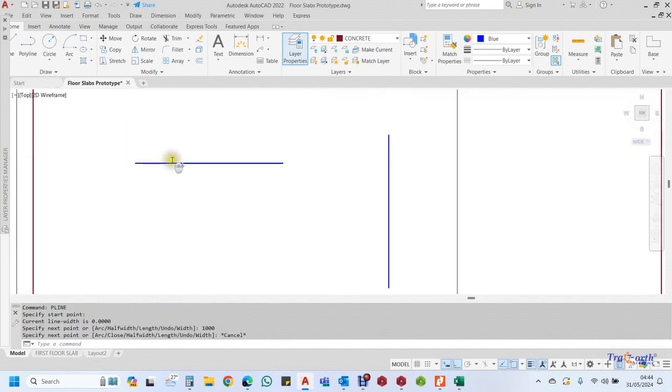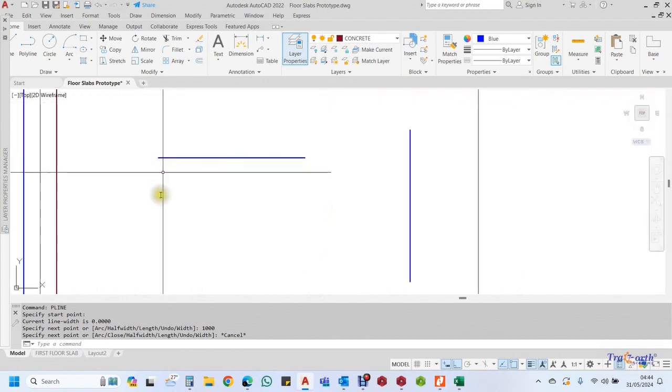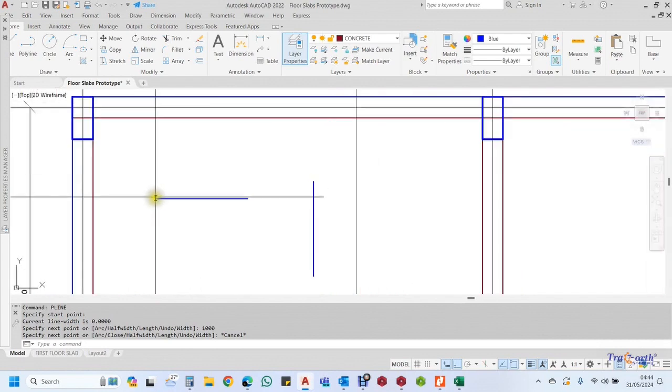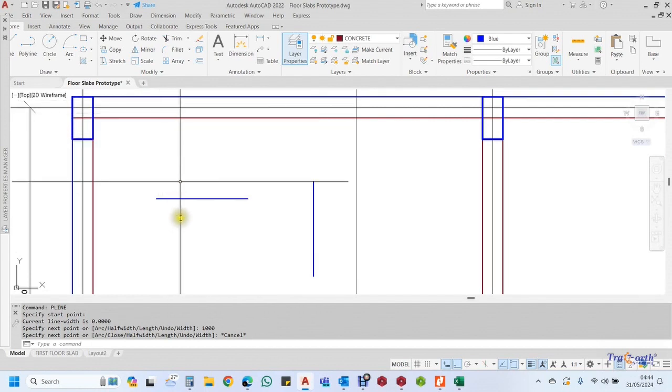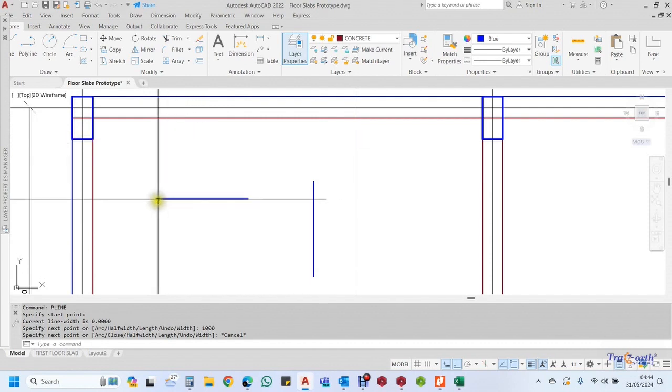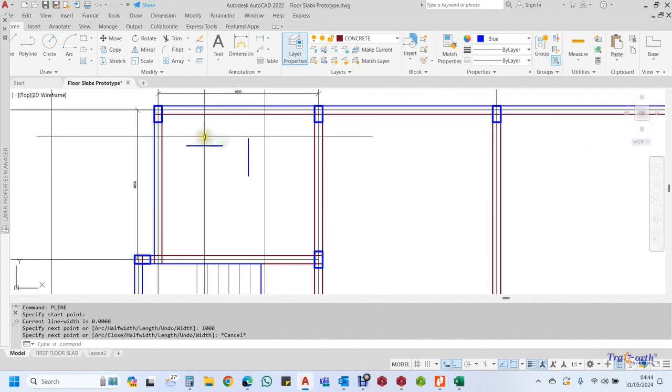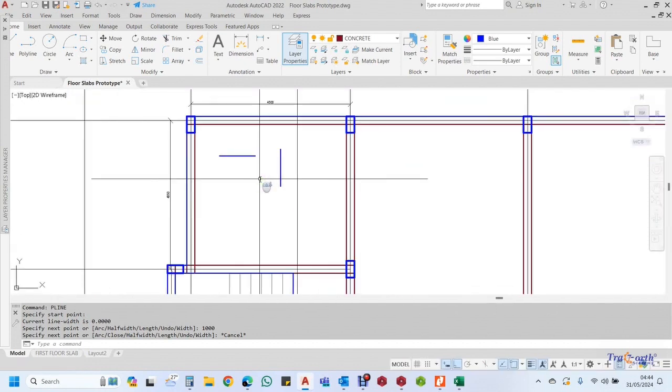So what it means is that when we want to detail this, or design this, from here to here is the width of our slab. That means in our y direction, we are going to distribute the reinforcement we get from our design within this 1 meter. But because this is a sample, we can equally apply it. By the time we begin to do the design, you will have a better understanding of this.